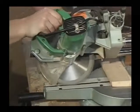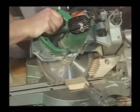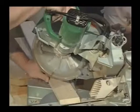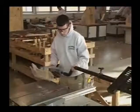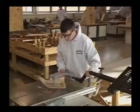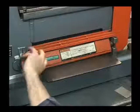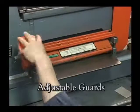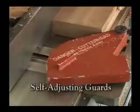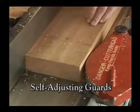So it is extremely important to use machine guards at these locations, but at the same time, the guards cannot interfere with the operation of the machine. For this reason, adjustable and self-adjusting guards are frequently used in these situations. Adjustable guards can be moved by the machine operator to suit their needs, while self-adjusting guards move automatically as material makes its way through the machine.